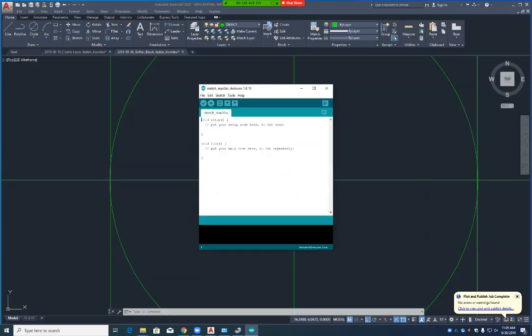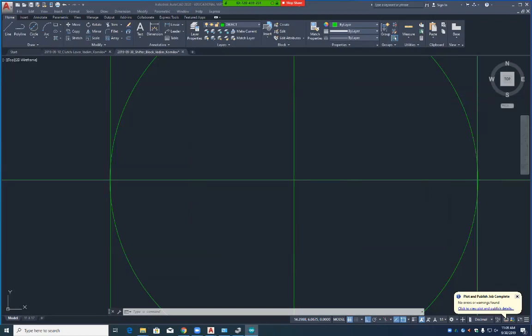The width, right? Okay, they told you that in the right side view, from here over to here is 1.31, right? Now, if that was centered, this would be 1.31 over here, right? If you add 1.31 and 1.32, you get 2.62, right? What did they tell you that was there? 2.63. Do you see the precision and your round off? That's what I'm trying to point out to you. How precise you want to get.